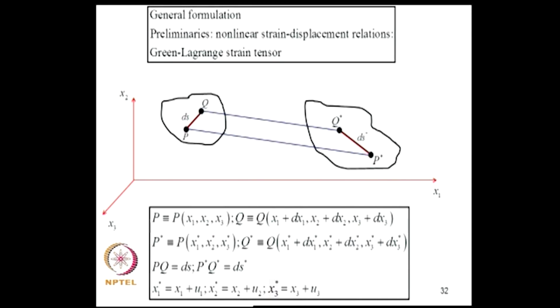Now, after this point we can take a traditional route and, for example, compute the geometric stiffness matrix for a 3D beam. So, a 3D beam has bending along two planes, twisting as we have seen earlier, and we can derive a geometric stiffness for that. Then we can move on to plate and other elements, but instead of taking each of these problems one by one, given that we already have experience in formulating these elements, we can take a look at the general formulation as applied for a 3-dimensional solid, and then we can specialize it to specific structures of interest. So, with that in mind, we will first start with the preliminaries.